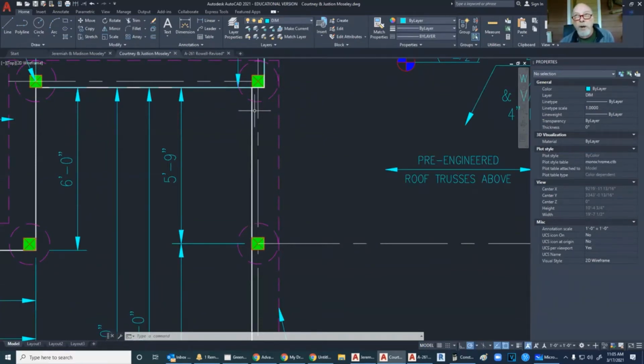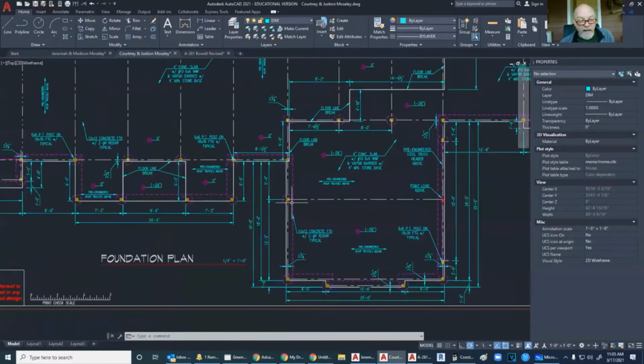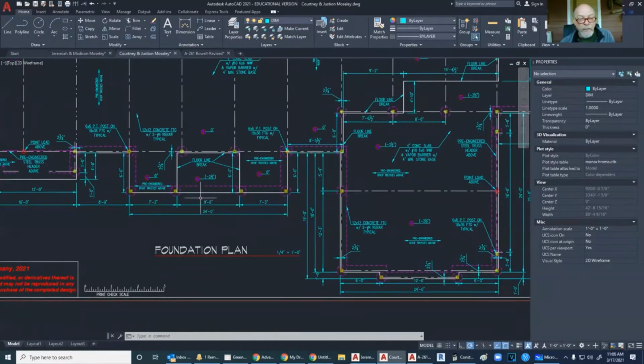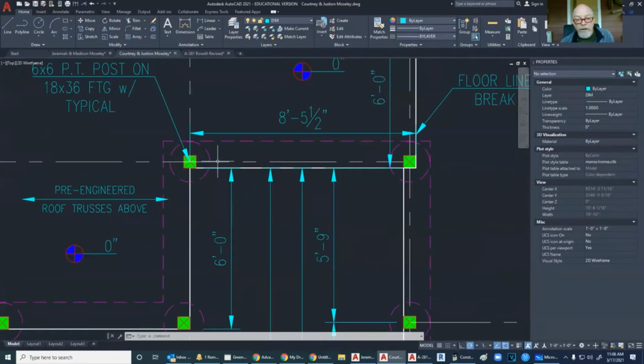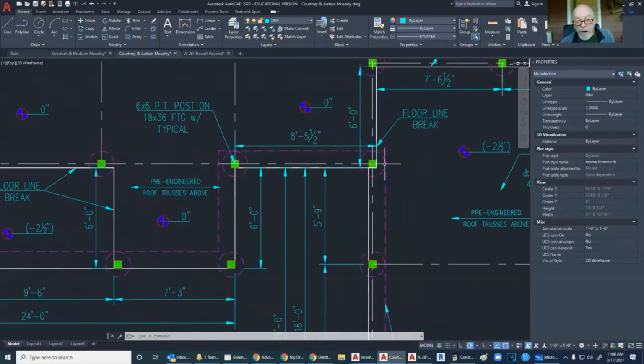That came out wrong. We don't have to have bearing studs. All of this inside is bearing free. So we don't have to have big headers in there. And we can slam insulation in here. We're using 2 foot. Well, technically we could use 4 foot on center. I wouldn't advise it, but I'm just saying we could because all the bearing is on the posts.